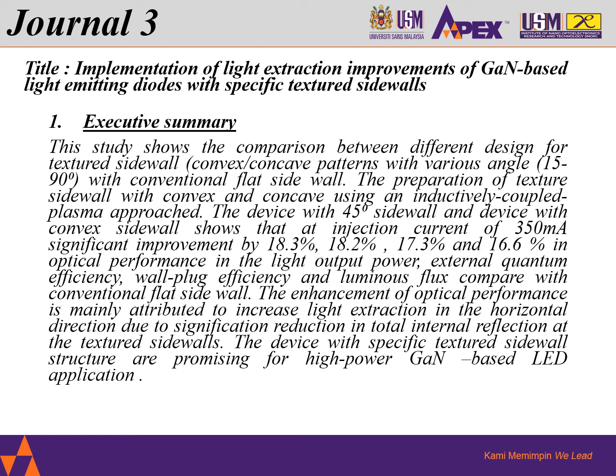In terms of light output, external quantum efficiency, wall plug efficiency, and the lumen flux compared with the conventional flat wall. The achievement of the optical performance is mainly due to increased light extraction in the horizontal direction, due to a significant reduction in total internal reflection at the textured sidewall. The device also can be promising for high power LED application.